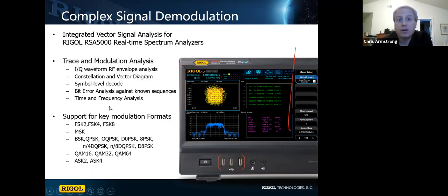So if you're looking at a signal with standard modulation formats like these, you can bring it into a mode where you're pulling that data in and setting the bits. So you're looking at the actual data being transmitted, and you're looking at the constellation diagram, so you can see what kind of noise is in that system, and it allows you to debug range and signal issues too, right? As your antenna gets worse or you get farther away from the source, your whole spectrum falls down, then you get more noise in the constellation diagram that starts to affect your bit rate.